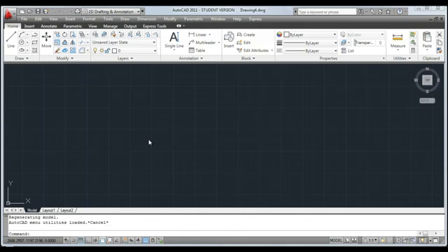What you should keep in mind before starting is that an A4 piece of paper is roughly 300 millimeters wide and 210 millimeters high. So you need the size of the piece of paper. The drawing border will fit onto the paper. So it's a maximum of 300, so we'll make the width 280. The height of the piece of paper is 210, so we'll make the height of our border 200.